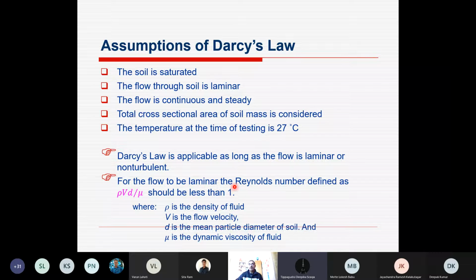You have not learned about groundwater, but let me tell you, in groundwater flow this Reynolds number increases up to 20 sometimes, because non-laminar flow conditions exist as well. In a pipe flow system, which we will learn when I pick the next topic, water conveyance and control in farms, the Reynolds number is considered laminar up to 2000 or less than 2000, because it's a pressurized flow condition. Beyond 2000, it's non-laminar. We will discuss that later. So these are the assumptions behind Darcy's law.